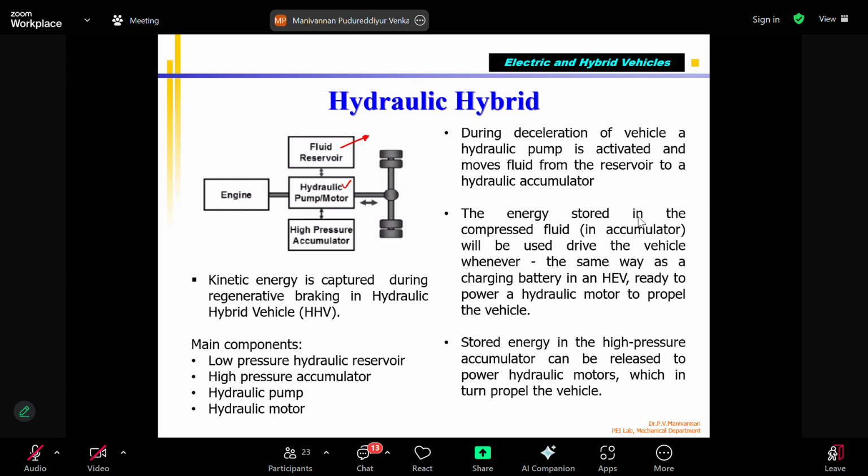We know that water, if it touches especially ferrous, copper, all those things, the moisture with the water can react and create ferrous oxide or copper oxide. We call it rust. It can damage the parts. So if you don't want damaged parts, instead of using water, you may use oils, different oils, correct? Natural oil, synthetic oil, some oil you can use. So that's what we use in many places instead of water. So when I say hydraulic, automatically it should be water based, but oil based also we call hydraulic only.